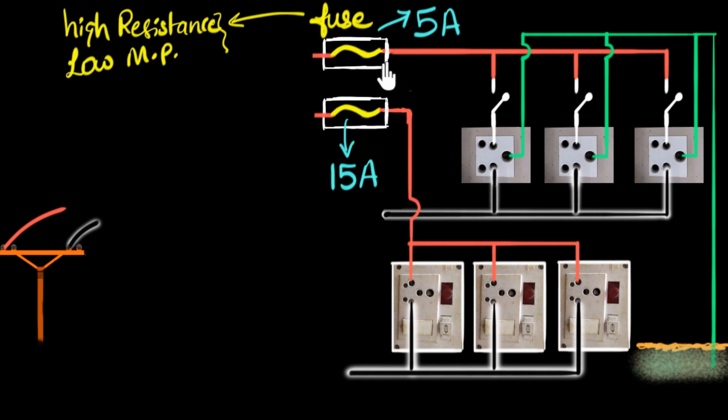So in our houses, we will have two independent circuits. One is 5 amps and another one is 15 amps. And of course, they should also have their own ground. Ground is definitely required, so all these grounds will be connected together. So will there be only 2 circuits, or can there be more such circuits? The answer is you can have many more circuits, each one with their own fuse. It all depends upon where you're staying, how big the house is, or whether it's a factory or things like that. But usually they'll have one 5 ampere circuit and one 15 ampere circuit.